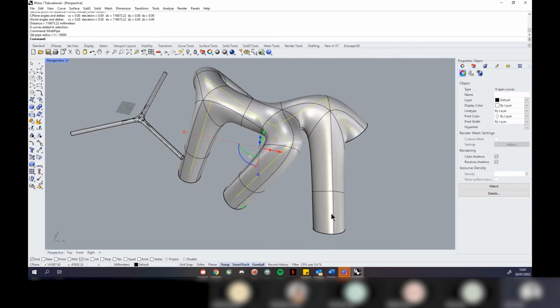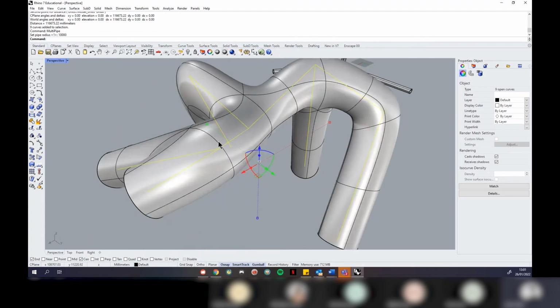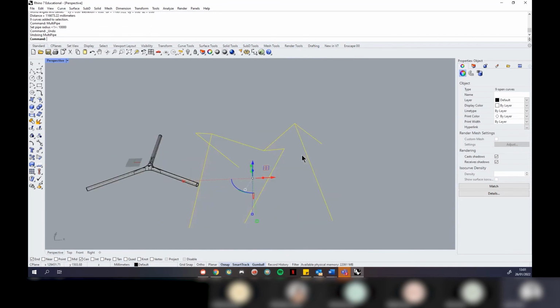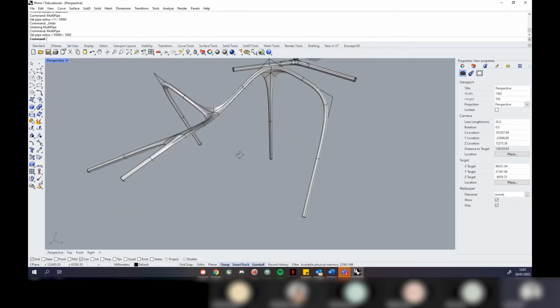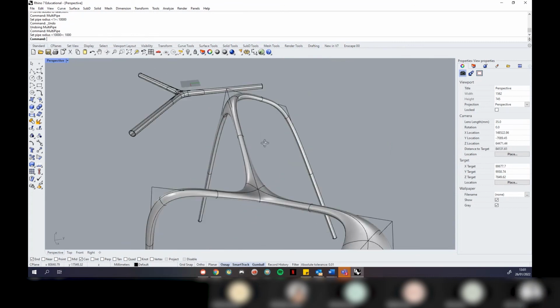So you can adjust the thickness of the struts. You can make these really thin. And you could tell the thickness of each of these nodes where they intersect to be thicker, for instance. And you can create some really interesting forms. If I bring this right down, maybe 1,000 instead of 10,000. Don't want to cap the endpoints. Strut divisions I'm going to keep set to 1 for a minute. You kind of see what I'm getting at with this. You know, create these kind of alien-like structures.